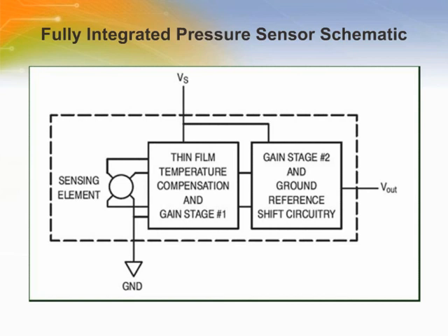The signal conditioning is accomplished by means of a 4-stage amplification network, incorporating linear bipolar processing, thin film metallization techniques, and interactive laser trimming to provide the state-of-the-art in sensor technology.